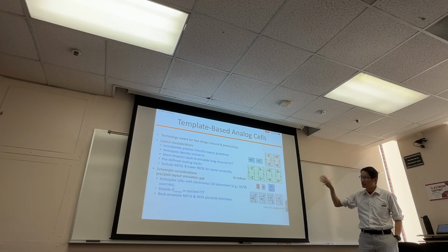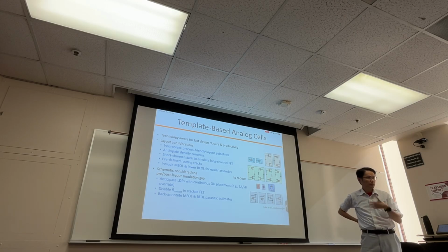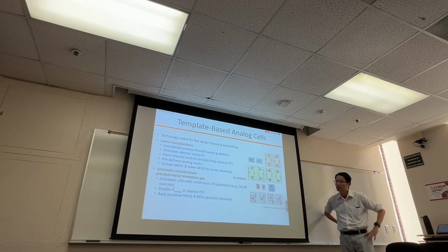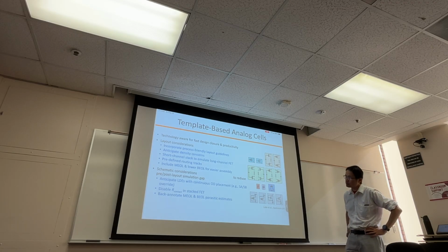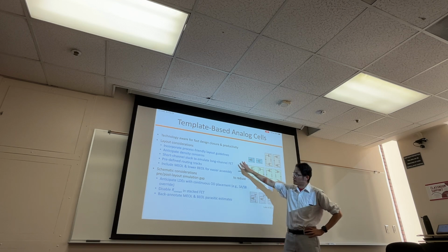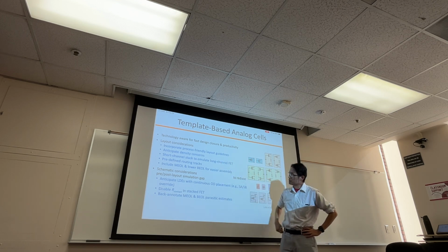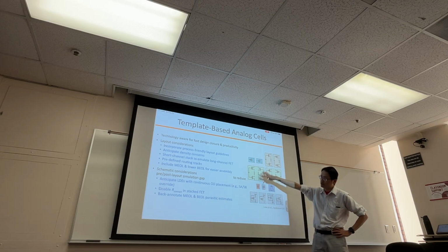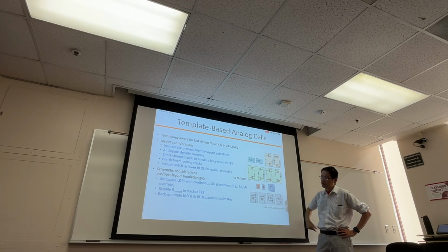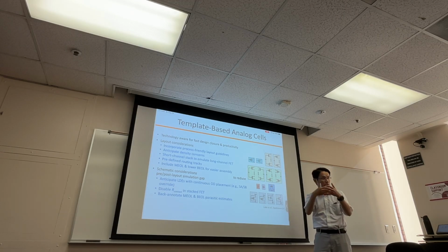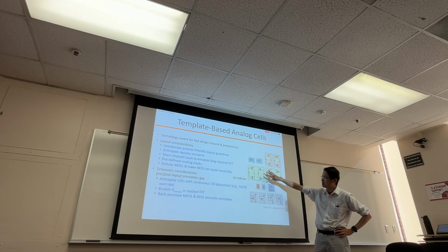Okay, so that seems to be what industry people are moving towards, right? So they all have this template-based design. So if one day you go to some company, you get to design some circuits in this advanced node, you wouldn't be too surprised if you see this kind of template-based design. Yeah, so they would incorporate these layout guidelines, all those density concerns. They do the same thing, right? So stack the short channel to mimic the long channel device, and even the routing, right? So the routing of those wires, they would also predefine.